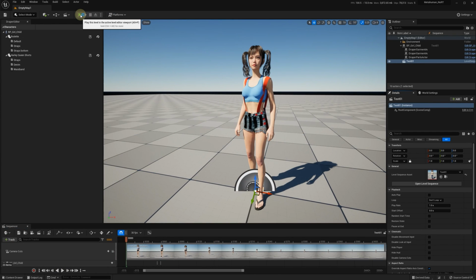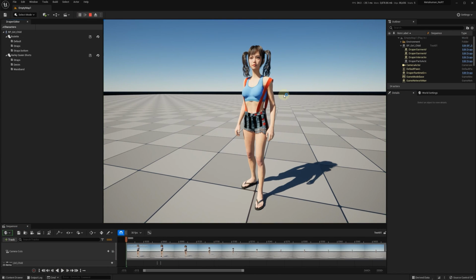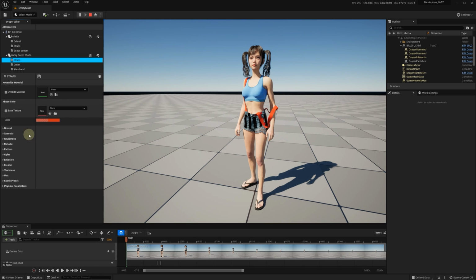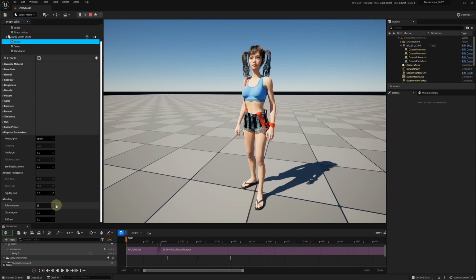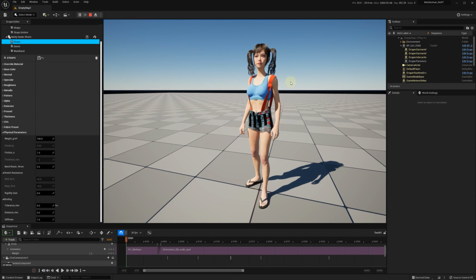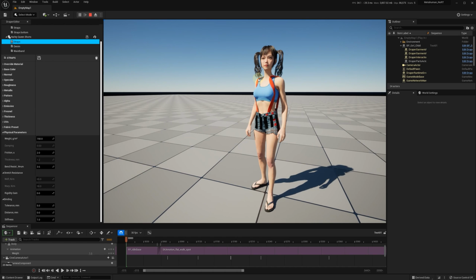In the next example we have these suspenders, which can easily slide down from the shoulders. Applying some binding will hold them in place and prevent them from falling. We also have the ability to toggle binding during the simulation by pressing Shift+B. This can be useful when we want to adjust the garment position at runtime. After the garment is positioned as required, we can save the garment and turn the binding back on.